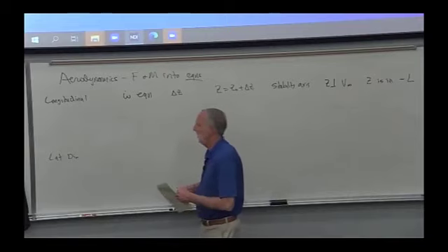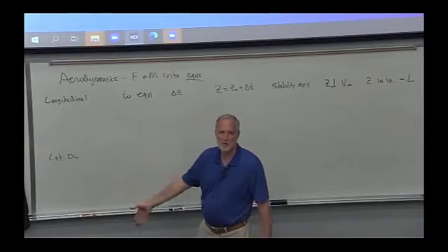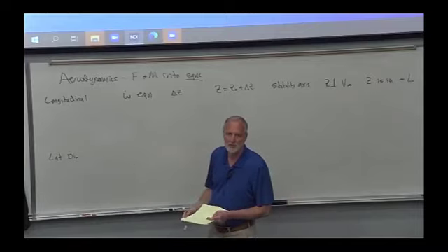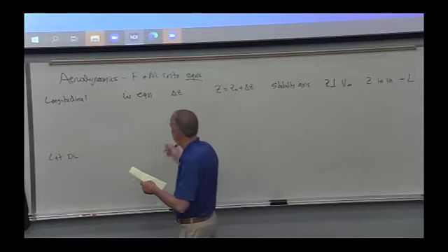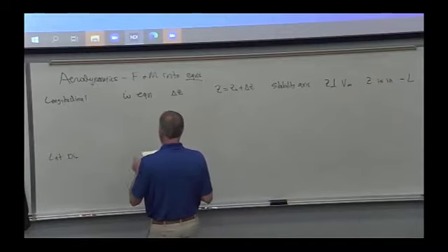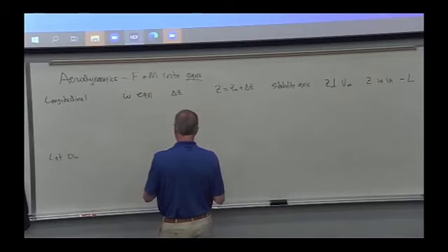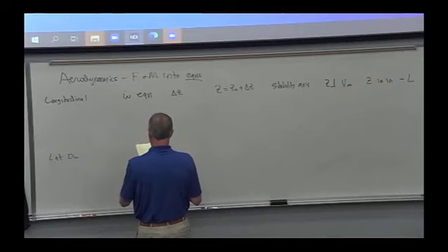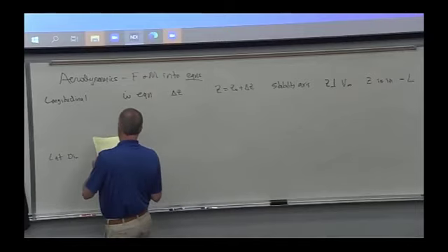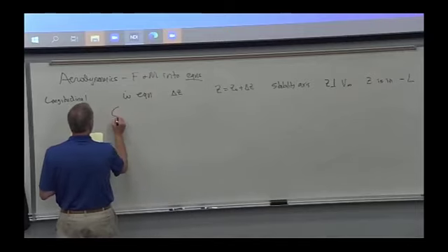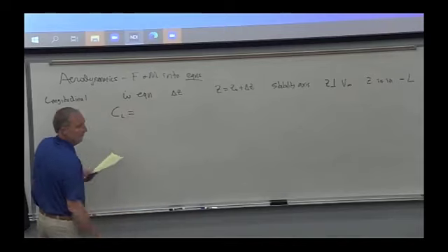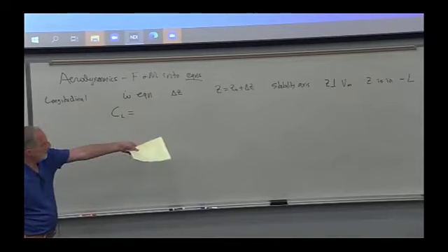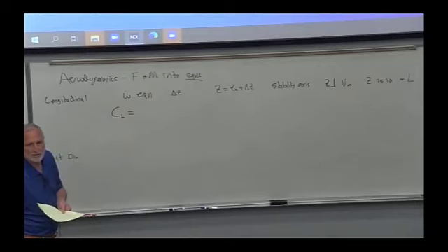Otherwise, you end up in the equations of motion with both components. You got the lift and the drag, and so the expression becomes twice as big. So that's the major reason people use stability axis in the dynamic analysis. All right, so we do just our normal build-up. What we need to do is calculate CL, because CL times Q infinity S is going to give us the lift, and that's going to be the negative Z.